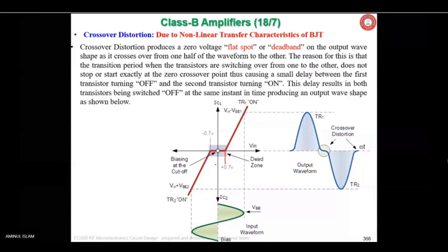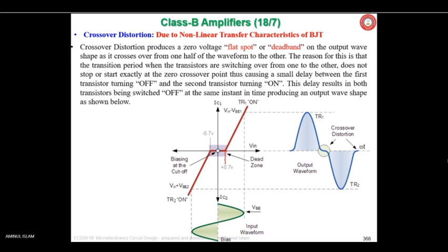See, it is the status of VBE up to this point. Here 0.7 volt is shown as cut-in voltage. In Millman and Halkias, it is given as 0.5 volt. Doesn't matter. The point is that up to this value of input voltage, VBE, there is no conduction. I mean, IC will not be there because IB is not there. So crossover will occur.